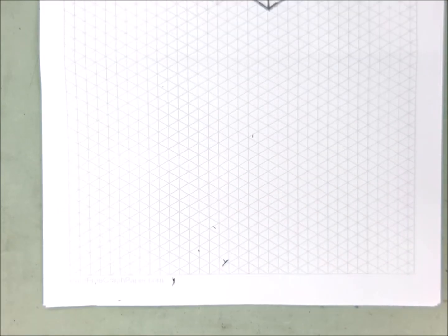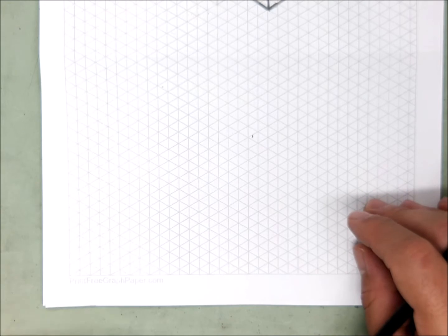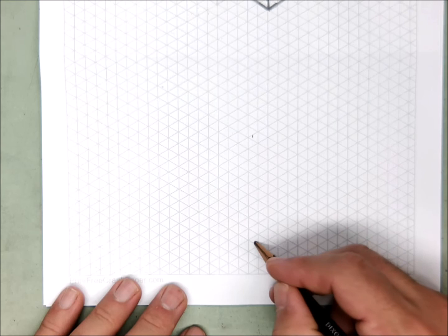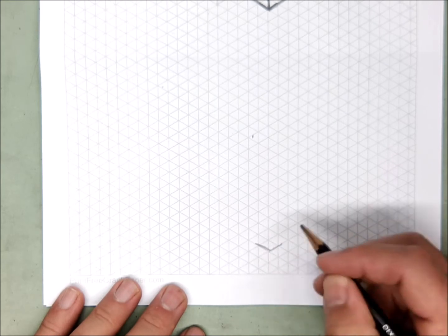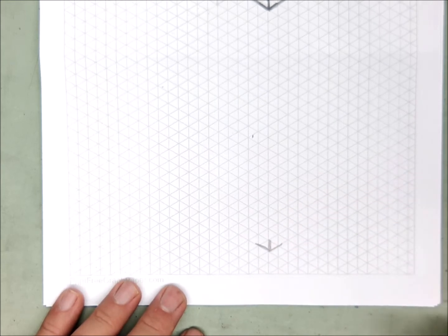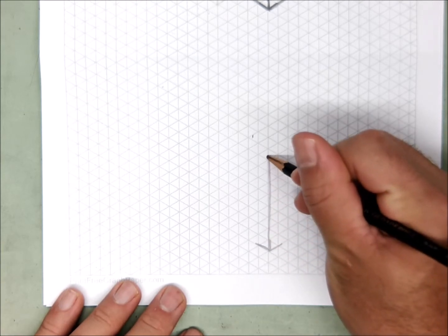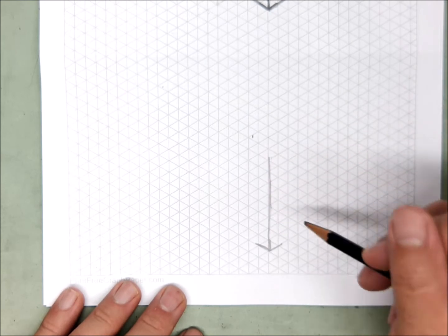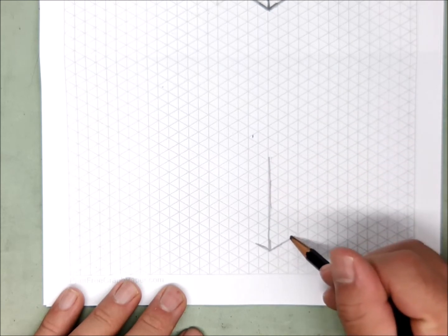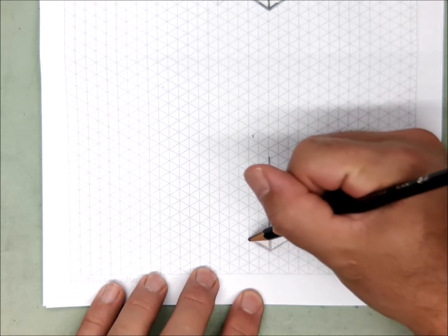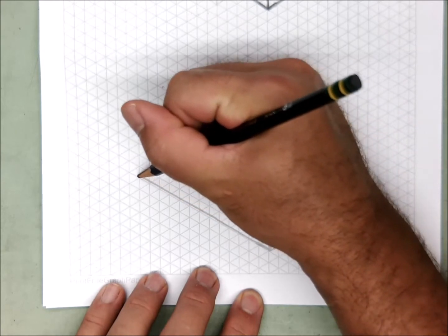Here's our next problem. Now understand, it doesn't matter what the shape is. As far as I'm concerned, the easiest way to do this is every shape starts off as a block. And you just chisel away at the block. So to make a block, you need a chicken foot, right? And then once you get the chicken foot, you make the vertical line for the height. You make the up to the right line for the depth. You make the up to the left line for the width.